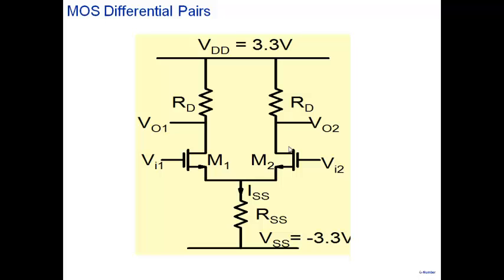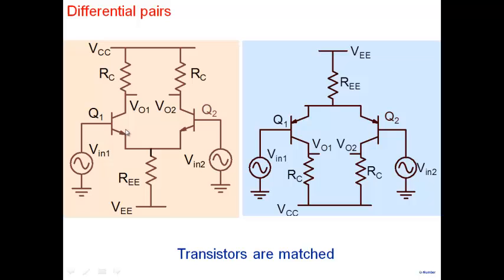And I'm sure you can imagine what I can do with this particular amplifier further. Note that this amplifier evolved, the way we did it, out of a common source amplifier. It evolved out of a common source amplifier with what? With a resistive load. Now, if you want to build a large gain, what can you replace RC by? You can replace it by a transistor. So I can easily replace it by a transistor here, right? Not only that, I can replace this by sort of a cascode pair here. Not only that, I can replace this by a cascode load also.